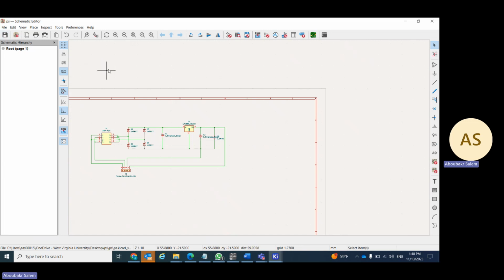However, if you are going to make a simulation, you have to add power supplies. So now you have the terminal block, correct? The block terminal will be connected in reality to your system. But if you would like to make a simulation, you have to have your exact supply, connected to your ground, connected to the AC source, and so on. Okay, so what I'm going to do is define some power terminals, which will help me during the PCB layout. So how can I do that?